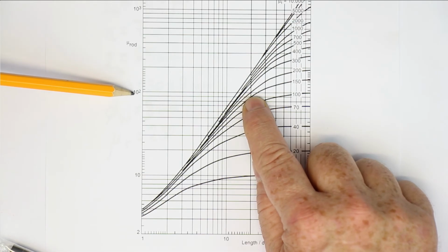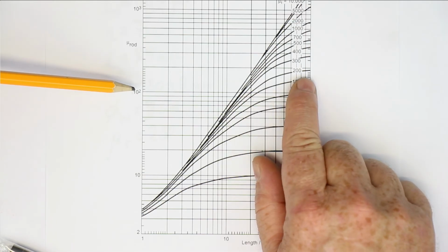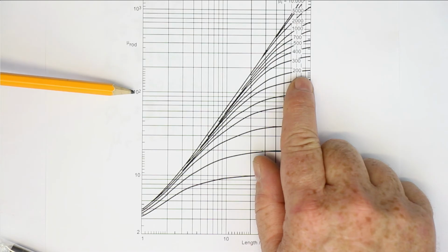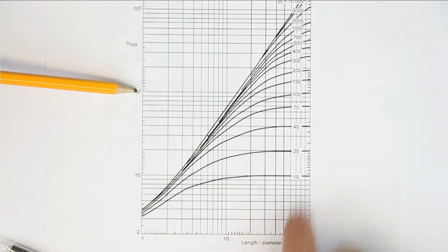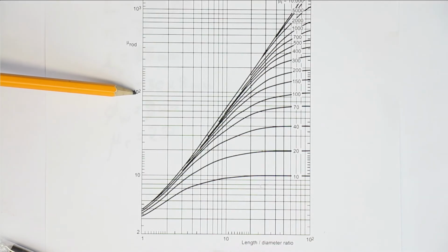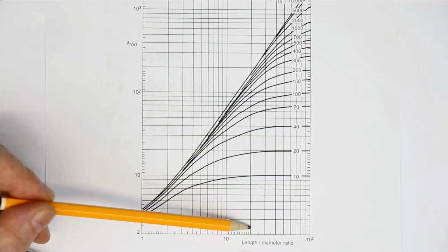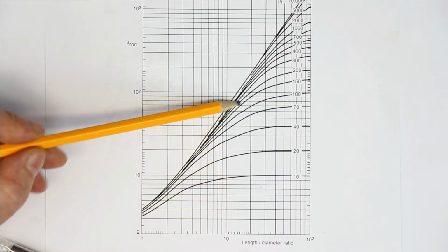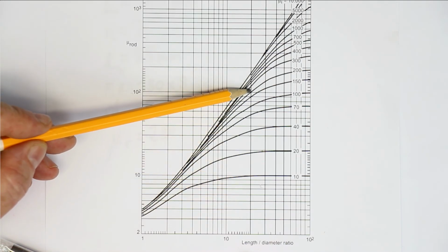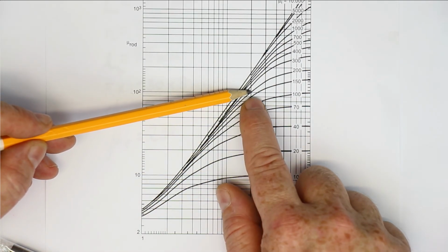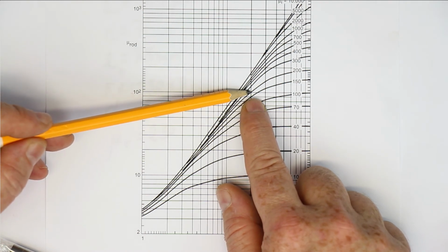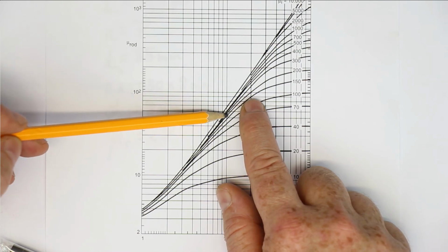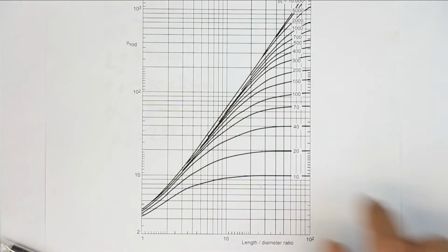So obviously we cannot take the full permeability of the ferrite material due to using a ferrite rod with a length to diameter ratio of nearly 20. We have to reduce this to around half of its value, from 250 to 100 or 125, something like that.